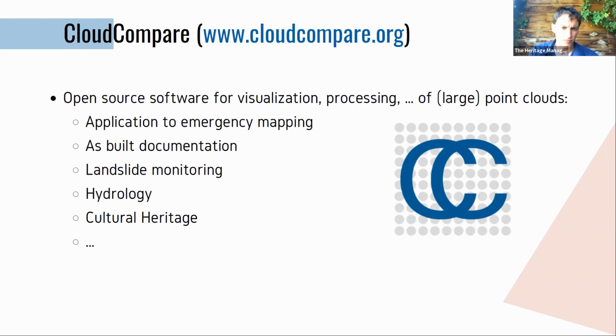For example, working with point clouds in AutoCAD Civil 3D is still not very convenient. On the other hand, there was software available like Leica Cyclone that I'm using with my Leica scanner, but also RealWorks for Trimble and, what's the name, I think it's Faro Scene for the Faro scanners. But this software is also quite expensive. So actually, if you want to work with large point clouds, CloudCompare is a very good and very useful alternative.